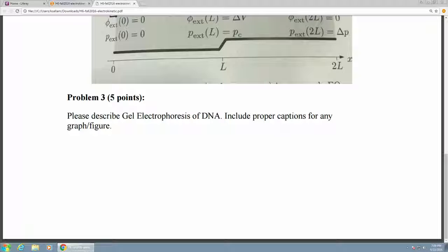Just keep looking at it. Personally, when I first saw this as a student, I was always confused by that velocity gradient, partial u partial n. That's why I keep talking about it a lot, because I remember how confusing it was for me why it's minus partial u partial y at one side, but partial u partial y at the other side. Until you realize that when it comes to the slip at the wall, they don't care if you are facing upward or downward. They just care about the normal, away from the wall. Yeah. Whatever is away from the